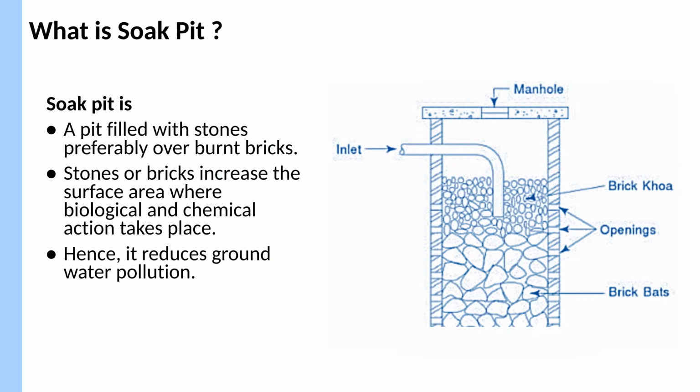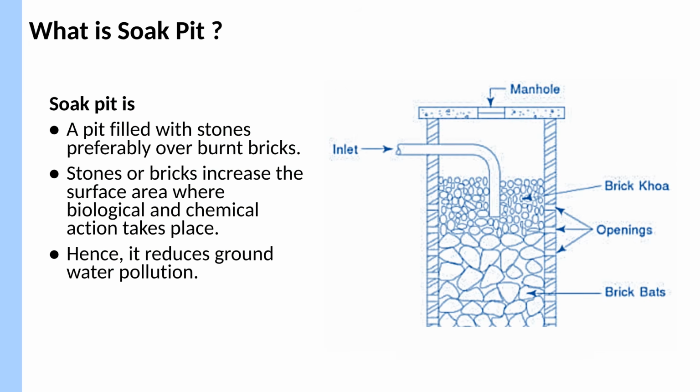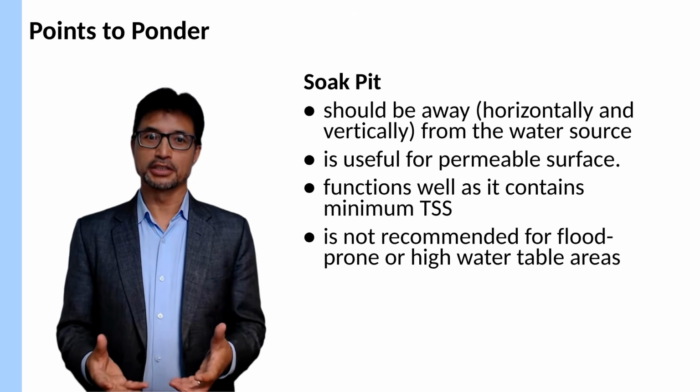Now let's design the soak pit. Liquid coming out of the septic tank is managed safely using a soak pit. A soak pit is simply a pit that is filled with stones, preferably over burnt bricks. These materials provide additional surface area where biological and chemical processes can take place. A soak pit, however, is not suitable everywhere.